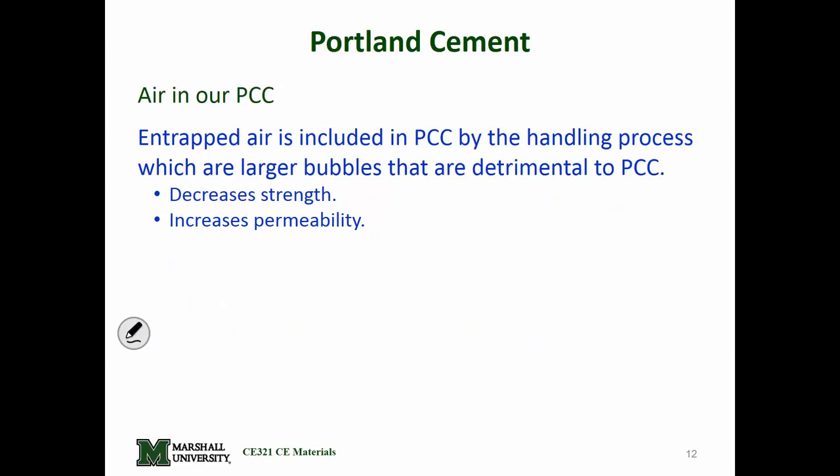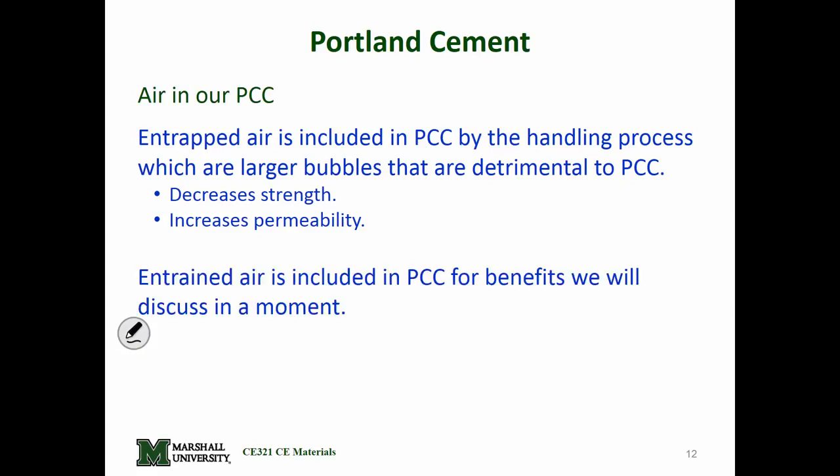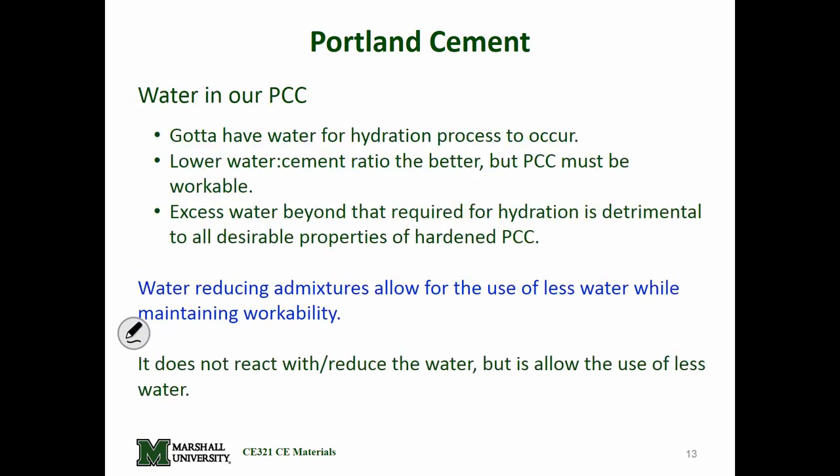We don't like entrapped air. It has all the bad effects. We don't want decreased strength and increased permeability, because the bubbles are connected. We do like entrained air. We'll talk about that in a little bit more.